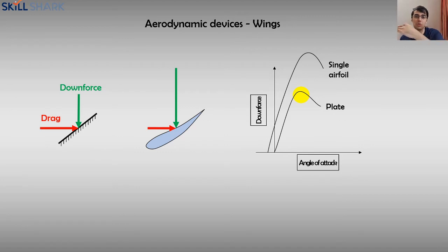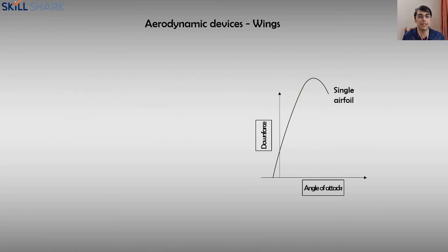If it's a flat plate, it's just going to cut through air, no real force is going to act. But in the case of an airfoil, it still has the ability to generate downforce even when it's at 0 degrees with respect to the flow. And we'll try to understand that with different scenarios. And as you can see in this visualization, you do have more downforce for a given amount of drag in an airfoil. So that is the lift to drag ratio, or in this case, the downforce to drag ratio. And generally in motorsport, you can either call it downforce or negative lift, because it's opposite to the direction of standard lift. Now these profiles are obviously used in aircraft to push the aircraft up, but of course we don't want that in a race car because it defeats the purpose of sticking to the ground.